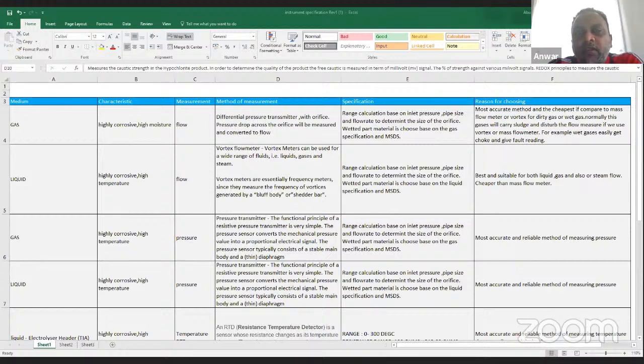Then you are able to choose the right material. When I say the right material, it is not necessarily all those extreme materials to achieve reliability. You have to choose the right material so that it can last minimally 5 to 10 years for the operation requirement, because a chemical pumping system will not be cheap.